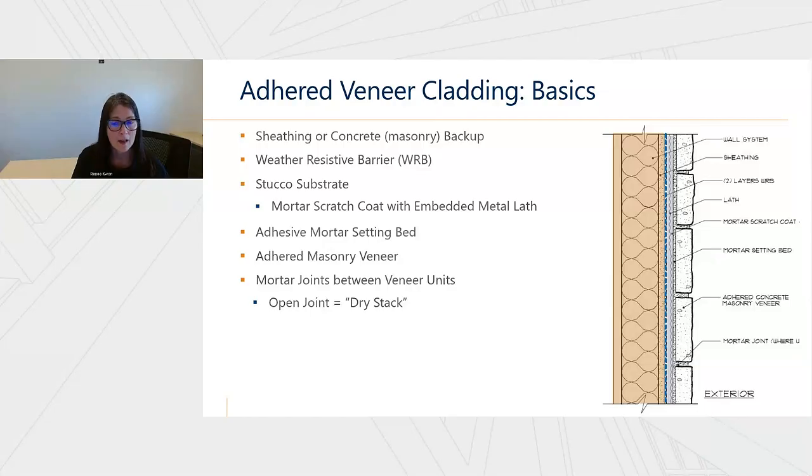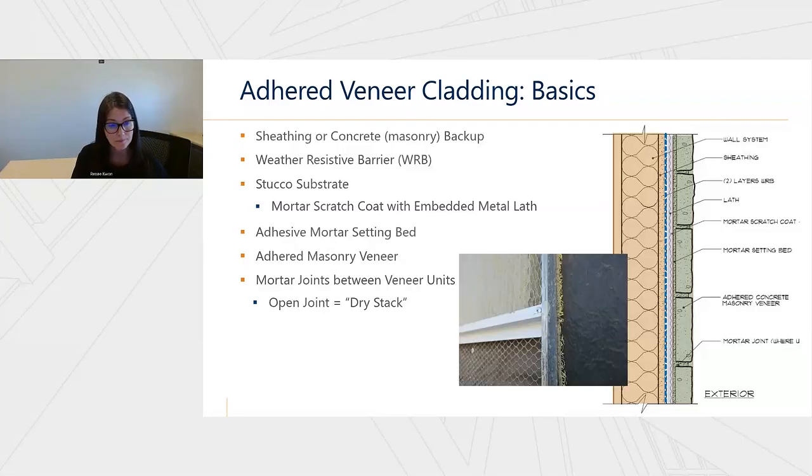Then outboard of that, in this example, we're using our backup as a stucco substrate, and this consists of a mortar scratch coat with an embedded metal lath. And that metal lath is going to be mechanically attached to our backup. Then outboard of that, we have our adhesive mortar setting bed, sometimes referred to as our adhesive mortar, sometimes called the setting bed. There's different language that's used to describe this component. But essentially, this material is going to be used to adhere our veneer units to our backup system. Then the joints between the units can either be pointed or they can be left open in a dry stack application.